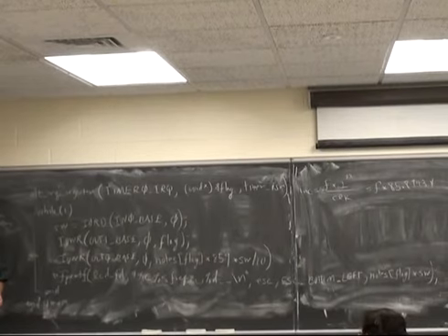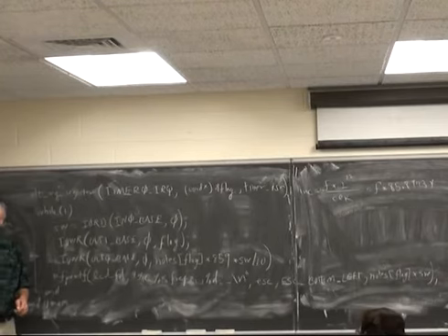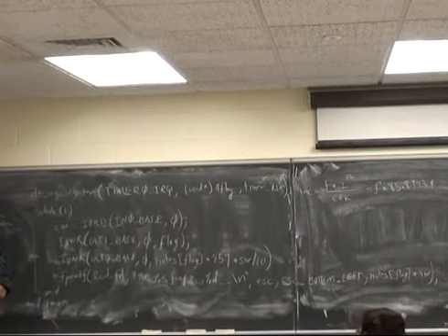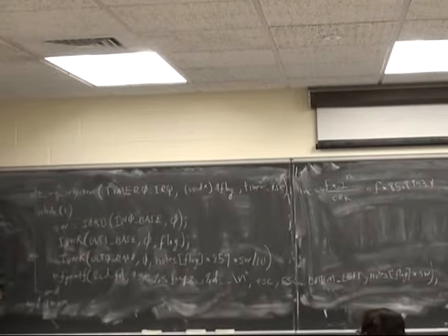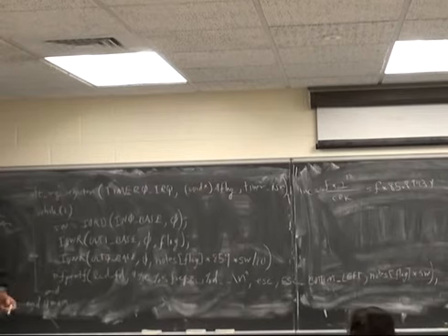But remember that if you execute off of SDRAM, there could be a memory choke point for multiple processors, unless you define the instruction cache big enough on each processor so that the first time through it hits memory, and then after that it executes out of cache. And then it could be very fast. You can specify the cache size in SOPC Builder of each CPU.